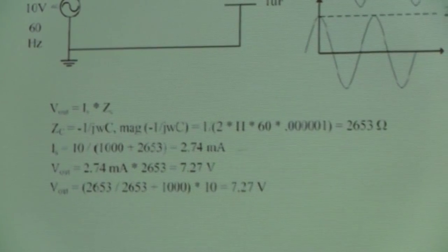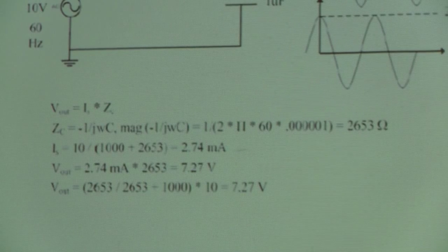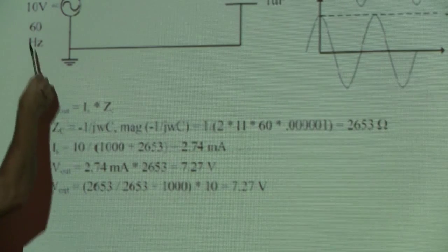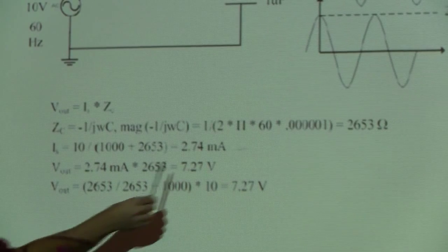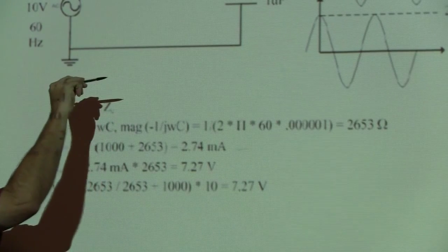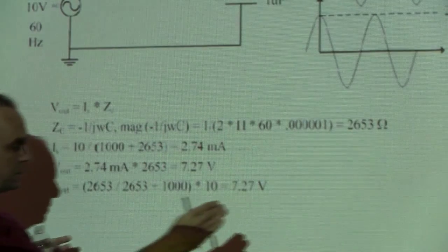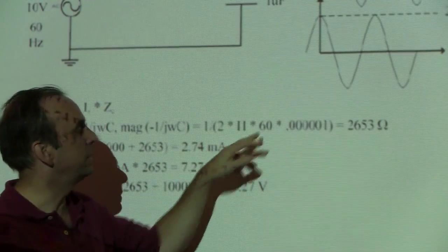So in this type of circuit where the frequency is fixed, as long as you understand that it's not exactly a resistor because it does have phase, at a particular frequency it sort of acts like a resistor. If I change the frequency, if I made this 100 hertz, 1000 hertz, a megahertz, then the impedance changes. This phasor that I showed you in the previous diagram moves, and the phase between the two changes. And actually I guess also the magnitude changes too, because the magnitude is here.